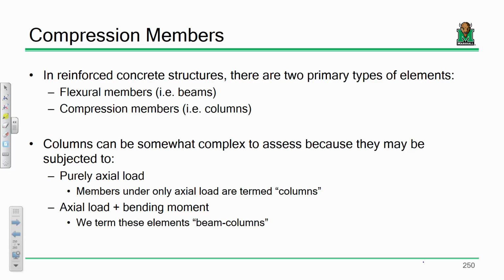As a result, columns are big, okay? And the result of that, we don't really have to consider buckling for most practical column scenarios. There are instances where we do if you have a fairly slender column, but a lot of times in concrete, we can ignore it. I'd say if you were designing like a 10-story tall building, yeah, you'd have to consider column buckling. But for simple bridge piers and whatnot, considering how big they are, probably not. Actually, not really.